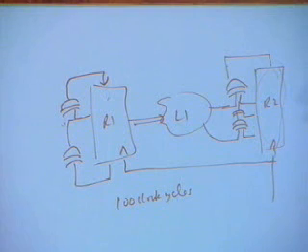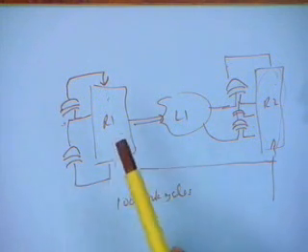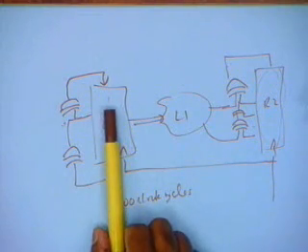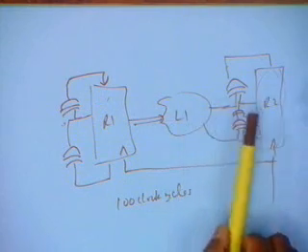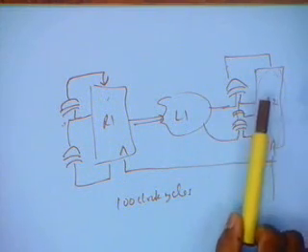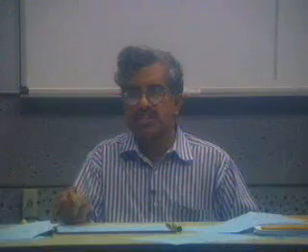Because I am generating the same 100 test pattern inputs and I am also running it for the same configuration starting from the same seed, what I will reach after 100 such clocks will be exactly the same number. Each time I should reach the same number if my circuit is correct.